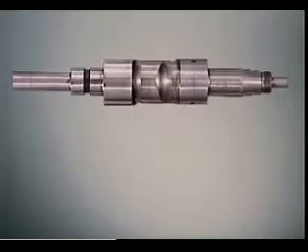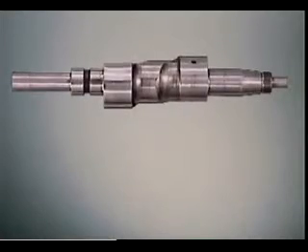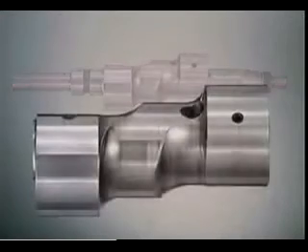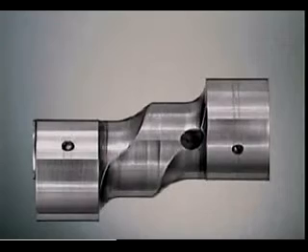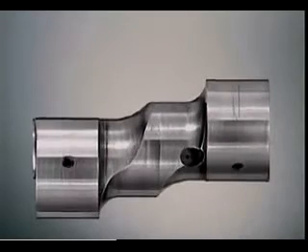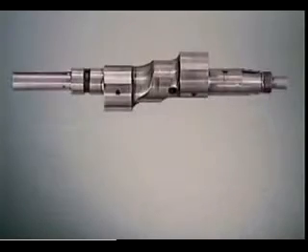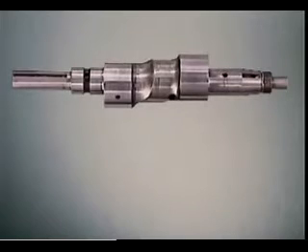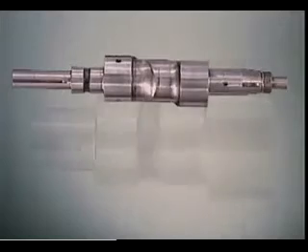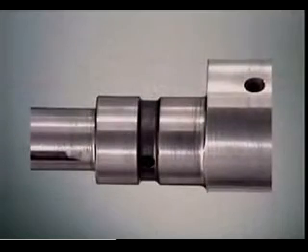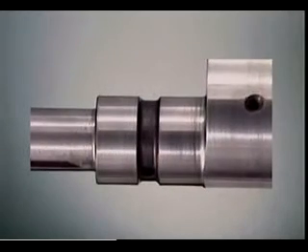The rotor is attached to an eccentric shaft at points called rotor journals. This shaft is like a crankshaft in a piston engine, but with the journals off-centre. Because the rotor is off-centre, the force applied to the shaft is off-centre too. The whole shaft is supported by main journals, so the final output is smooth rotary motion.